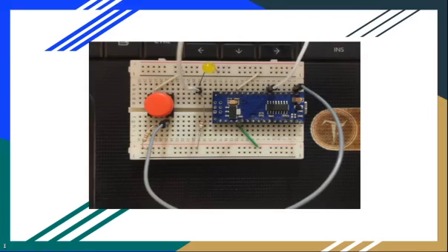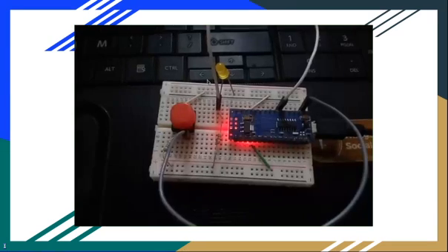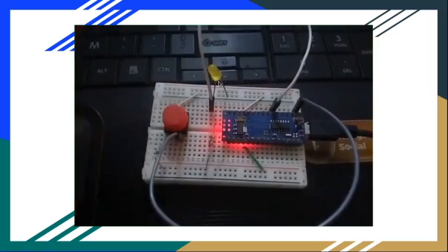So basically, let us just see. First of all, I'm having this circuit, and this is an Arduino Nano, and these are two pull-up resistors. This green wire is for the 5 volt, and these small white wires are the common ground. This is the push button for input. This is an LED for the output. This is pin number 12, which we initialize as an input, and I'm going to read from the state of this push button, and this is pin number 7 as an output, which is used to blink this LED. So let us just see our output. When we press this button, we are right now able to blink this LED.